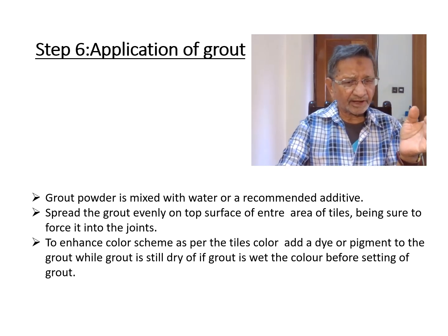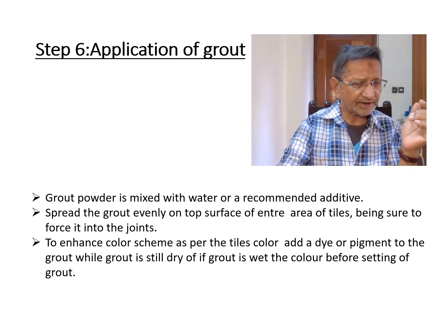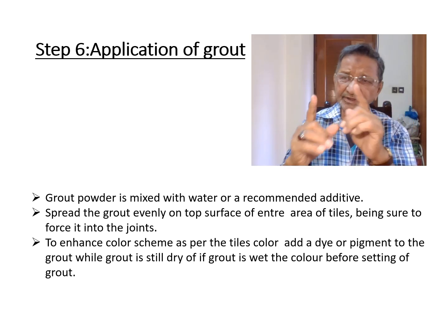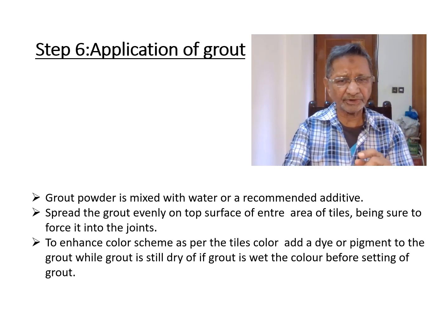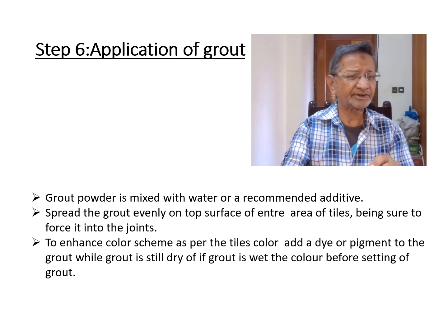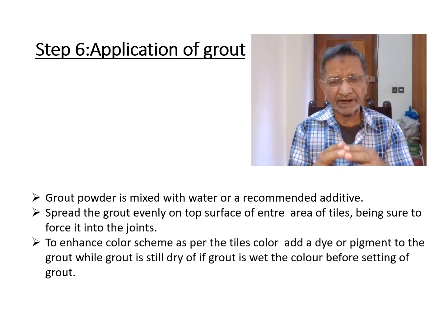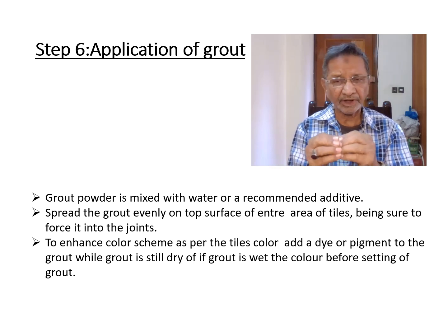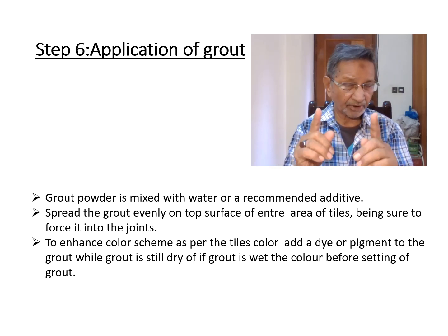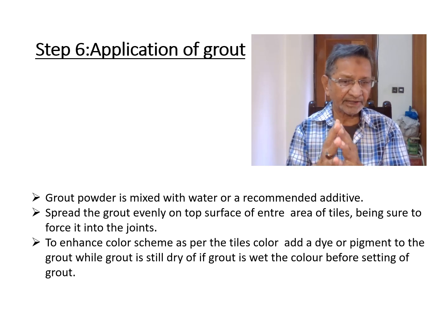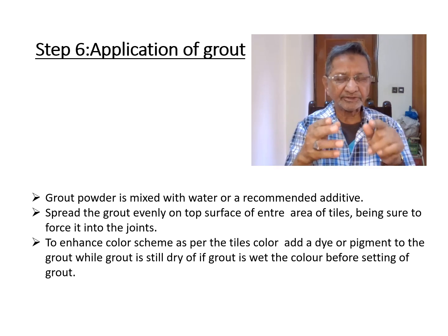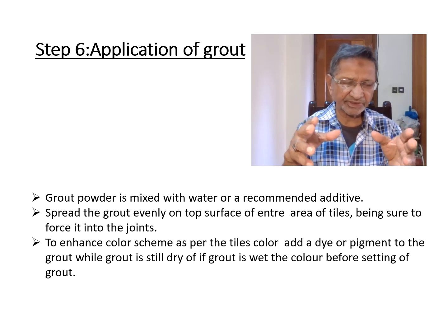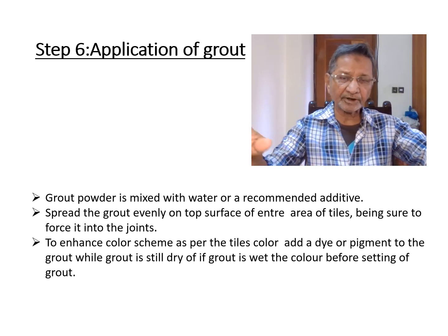If the grout is already wet and colored before it begins to set, don't allow anyone to move on those tiles, so that the tiles are not disturbed and no dust accumulates with the grout. Just a very important thing I would like to highlight: in joints, sometimes due to workers moving on the tile, it is not covered properly.